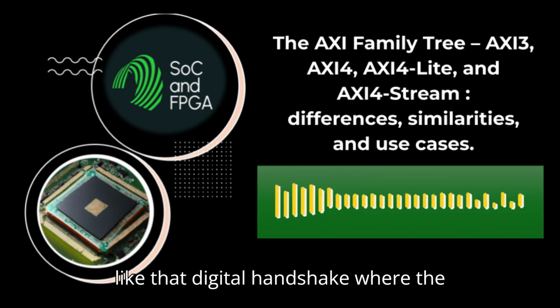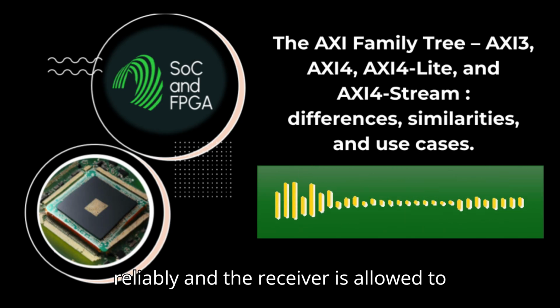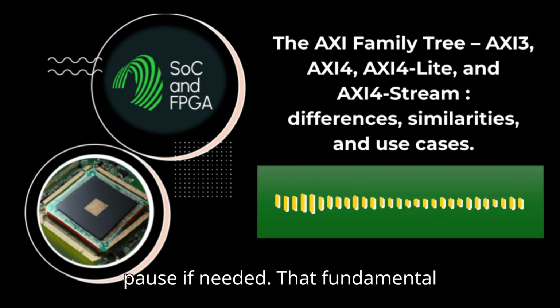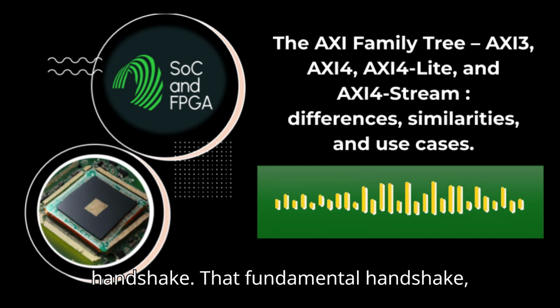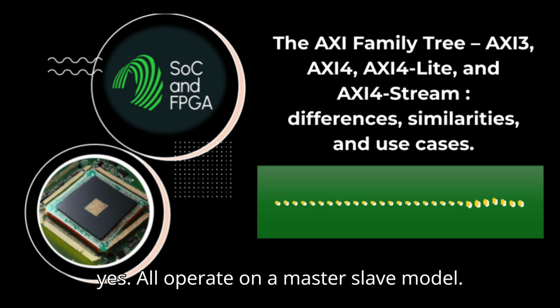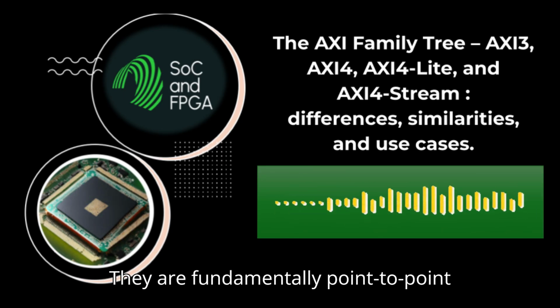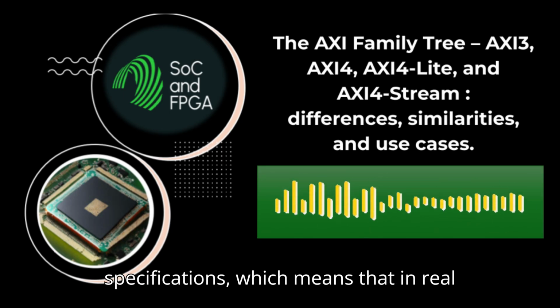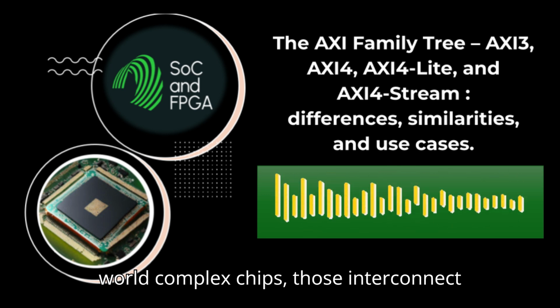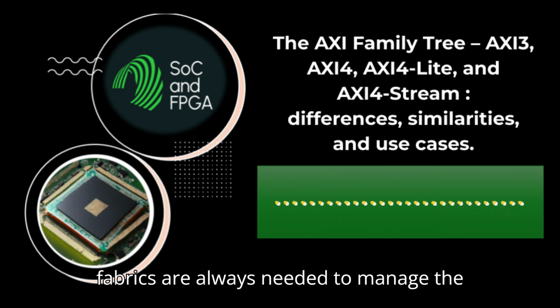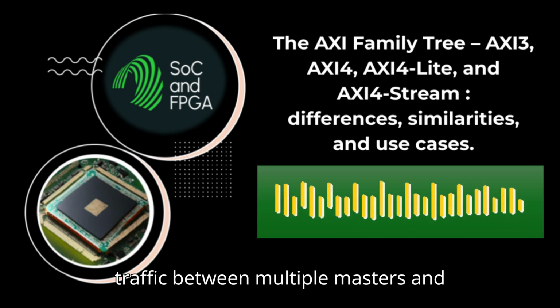It's like that digital handshake where the sender just puts the data out there reliably and the receiver is allowed to pause if needed. That fundamental handshake. Yes. All operate on a master-slave model. They are fundamentally point-to-point specifications, which means that in real-world complex chips, interconnect fabrics are always needed to manage the traffic between multiple masters and slaves.